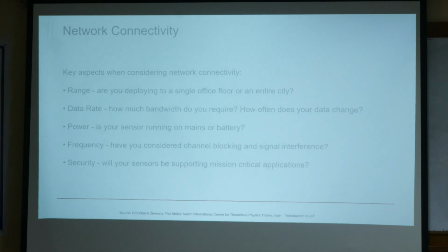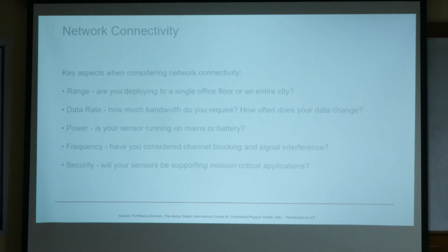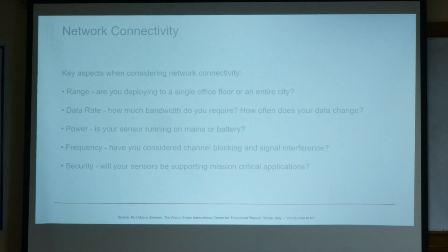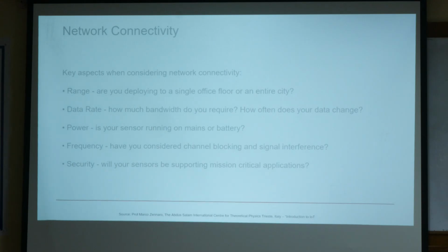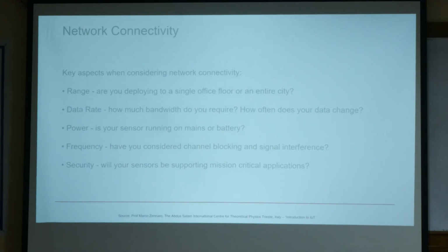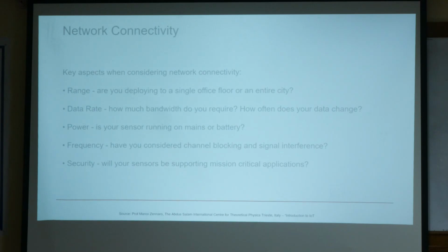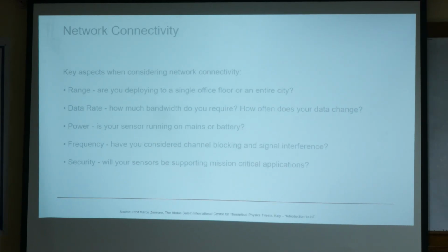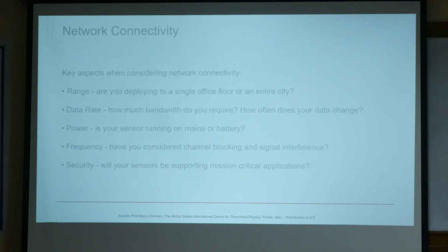So we are using a LoRa network structure and trying to do that, but that is the key. The range plays an important role. If I use Wi-Fi and Bluetooth, it is not possible for me because I cannot put too many Wi-Fis along the way and go there. So the best architecture should be LoRa because the range is in the kilometers, right? So the range will tell you what type of network you are supposed to pick.